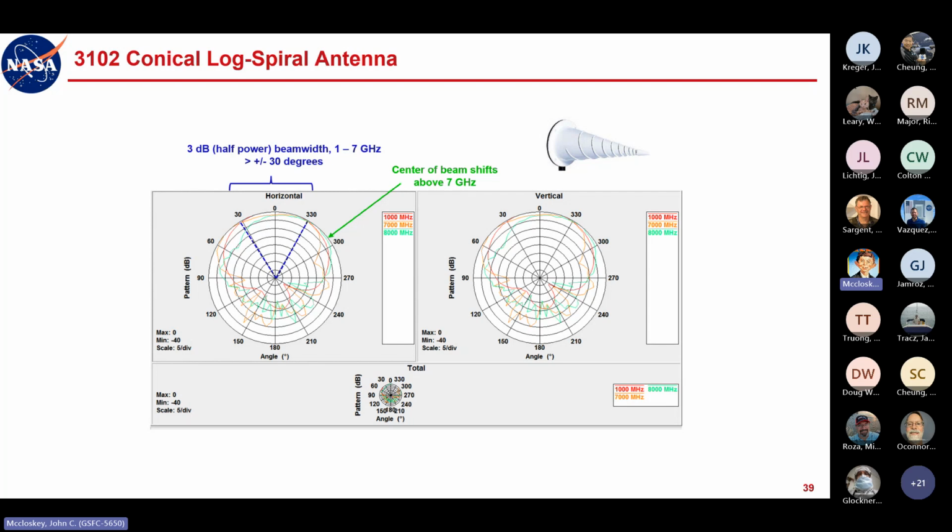I don't think you're generally dealing with like a 2 or 3 dB level problem at that point. But there again, just use the information at your disposal. These antenna data sheets are readily available. Just look up the parameters for the antennas that you're using, and make an informed decision about the test antennas you want to use on the antenna position.